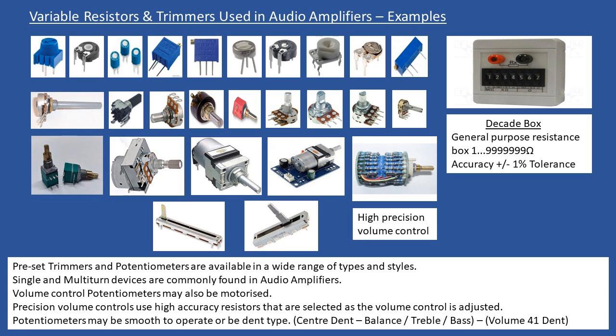And then I can increase or decrease the resistance value, and at the same time I'm measuring very accurately across the emitter resistors, commonly on the output stage, and then I can adjust the resistance to the value required to set the appropriate bias, and then depower the amplifier, and then I can make up the required resistance value using a couple of high precision fixed resistors, and that's really what the decade box is being used for.